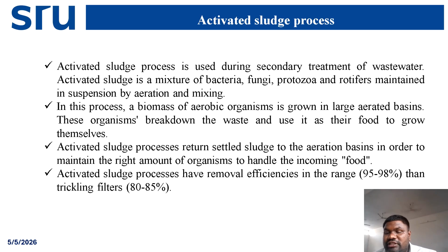Then, to maintain the ratio of microorganisms to organic matter, some of the returned sludge we need to send back again to the aeration tank. This is the recycling ratio. Recycling means that after treatment, the sludge needs to be sent again to the main tank, so that ratio needs to be calculated.